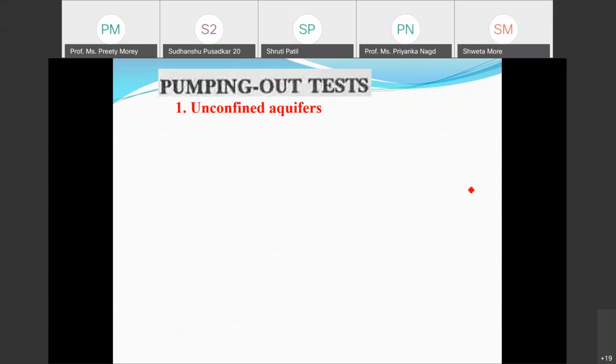However, the integrity of the soil mass, or the complexity of the soil mass which exists in the ground, will not be able to be created in the laboratory. And hence, for important structures such as dams, you have to conduct certain field tests. Those tests are conducted in situ and over a large area, and thereby we will get the exact content of the soil mass and the permeability of the soil.